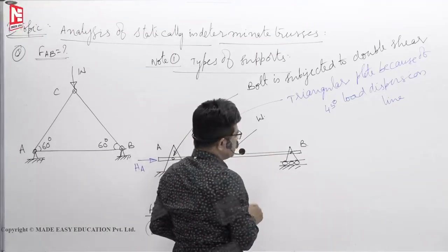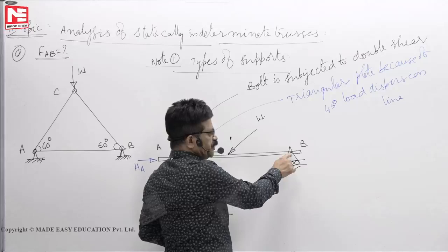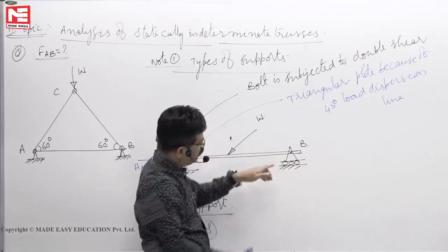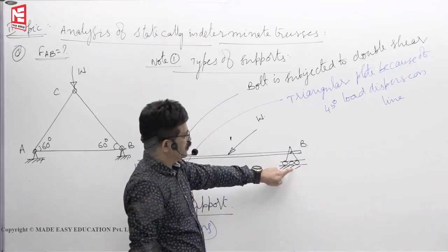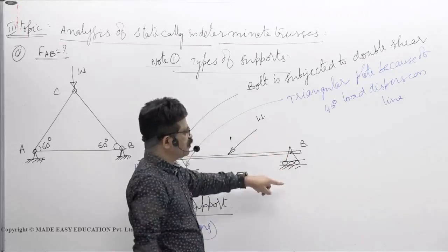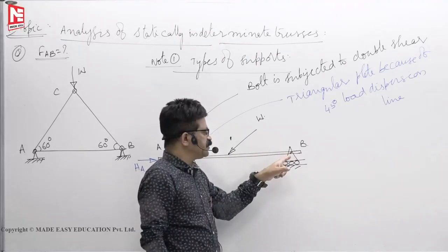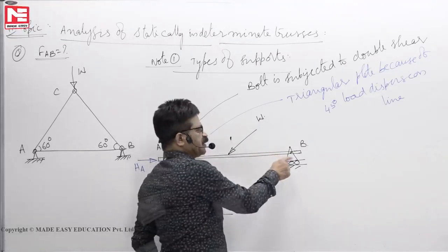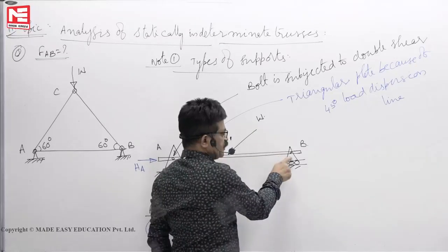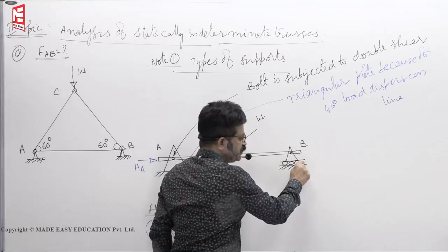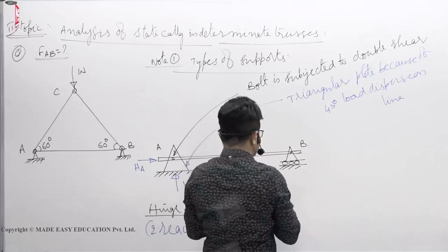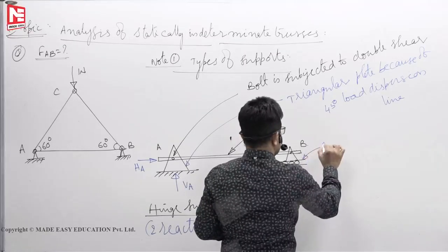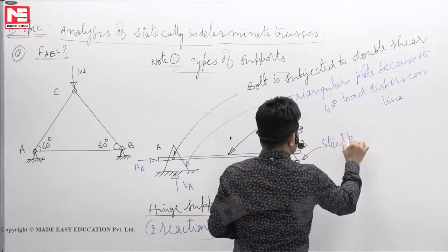Roller support. For a roller support, if the height between the beam and the column is sufficiently large, then you will bolt a triangular plate as in this case, and the triangular plate will have a base plate. This is a steel base plate.